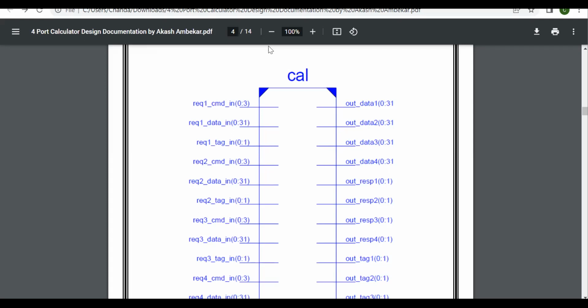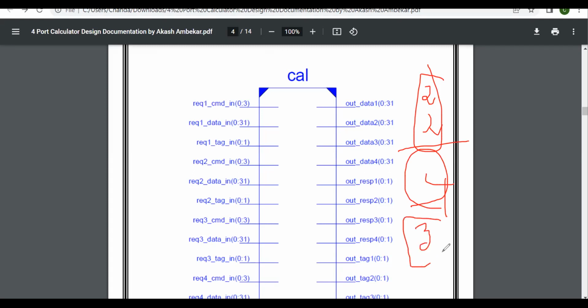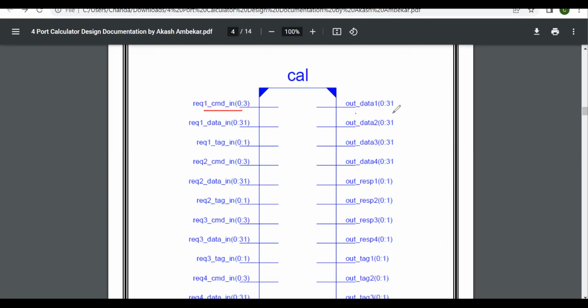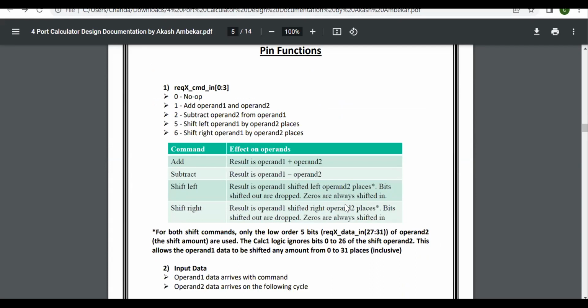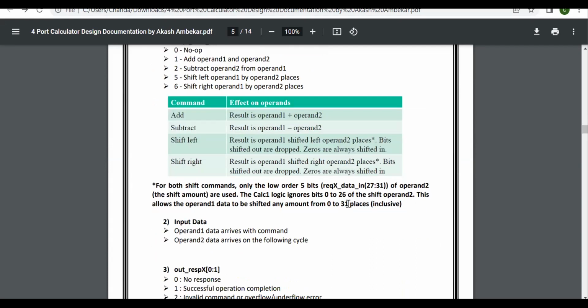We cannot, when you are doing the addition operation. Suppose you are doing addition with 2-bit input size, but the output you will always declare as a 4-bit size, because 2 plus 2 you may get 4, which is under 3-bit, right? So that's why input and output size will not be equal when we do addition, subtraction, multiplication and shift operations. The output size value will increase when we do those operations, right?